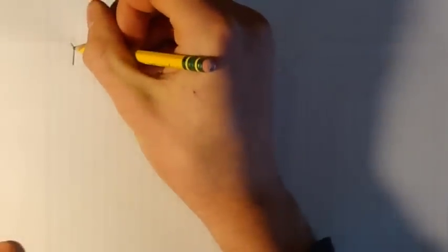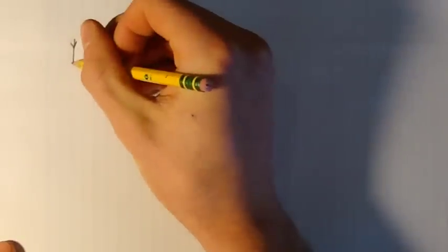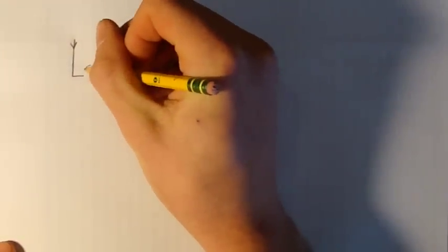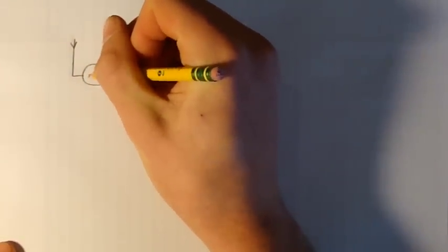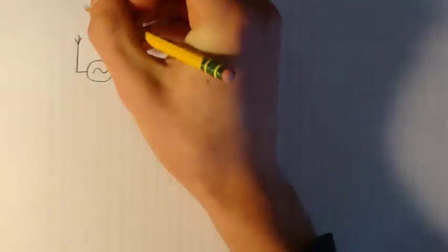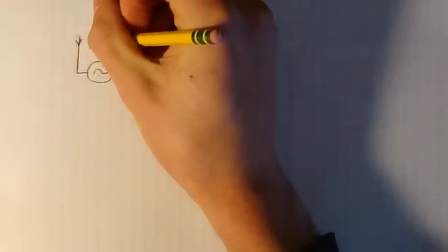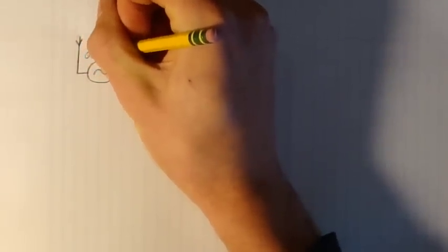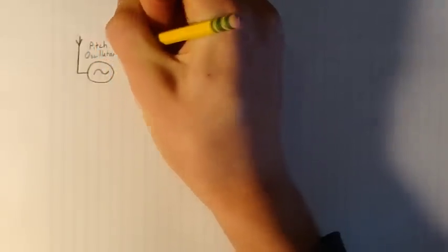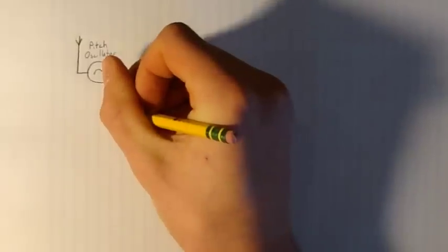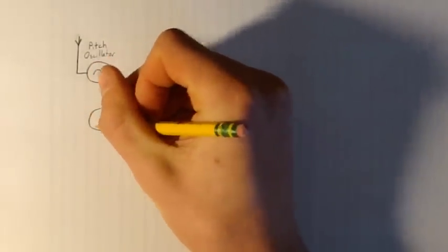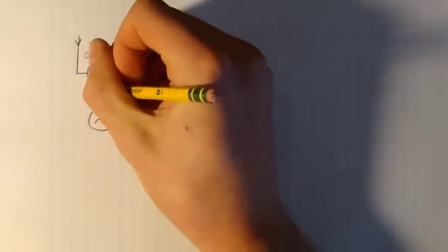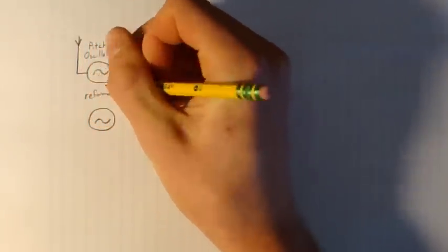Now, the antennas do not receive radio signals as you might suspect. Actually, they operate as a capacitor. The antenna itself forms the anode of a capacitor, and your hand forms the cathode, connected to a virtual ground, which is your body. This capacitor is variable, and the distance between your hand and the antenna changes its capacitance. This changing capacitance is what changes the frequency of an oscillator.